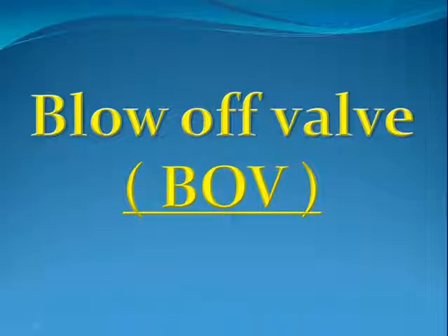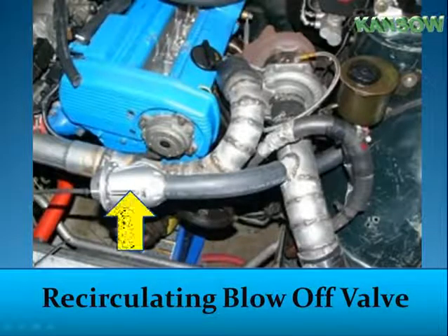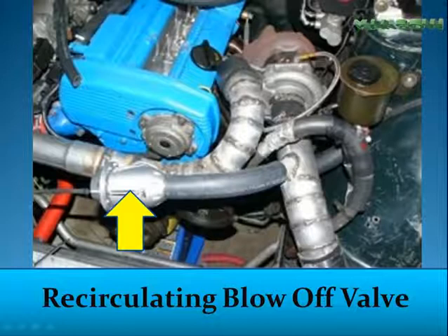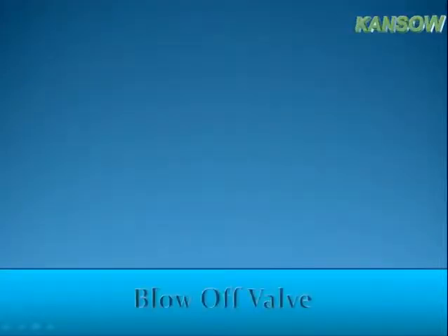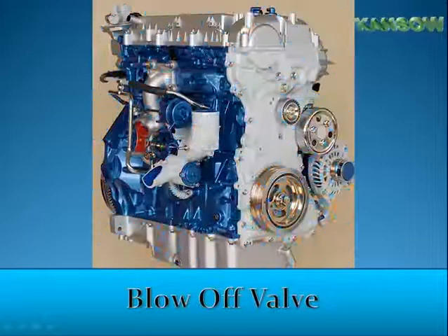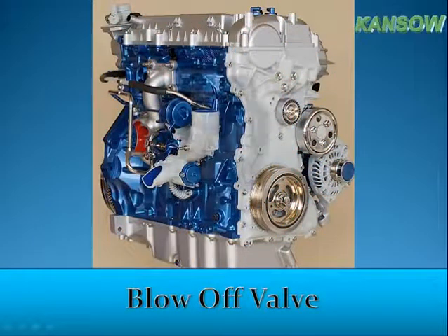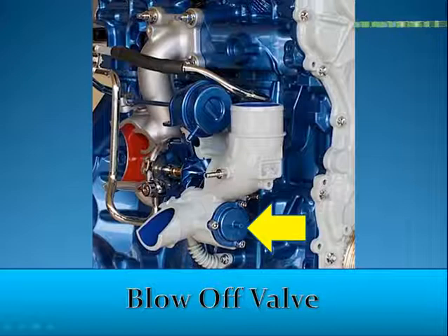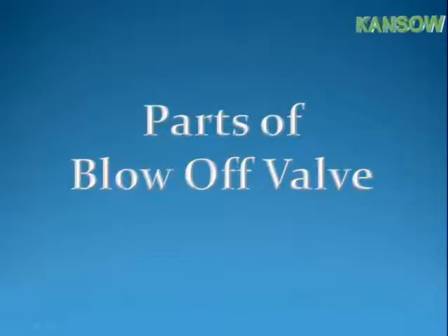high pressure air. Blow-off valve. A blow-off valve is an important part of any turbocharged vehicle. These valves save our forced induction components. These valves open whenever there is enough boost pressure in the intake pipes and vacuum from the intake manifold. When this valve opens, it releases the pressurized air in the intake piping either back to the turbo intake piping or vents it to the atmosphere.